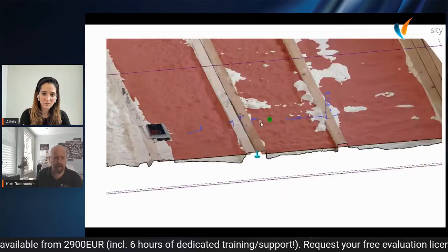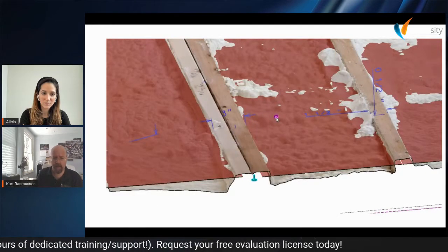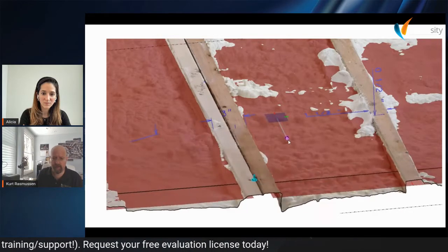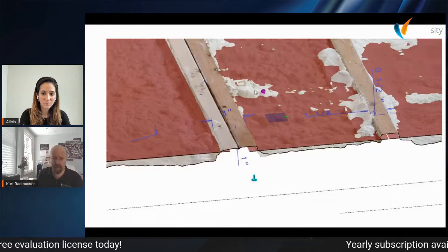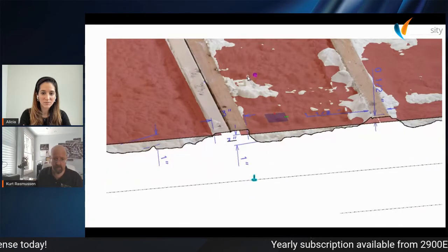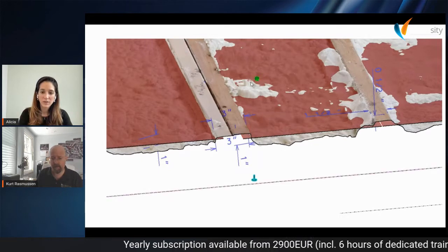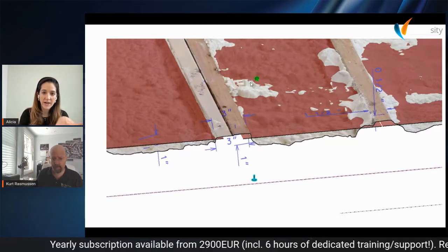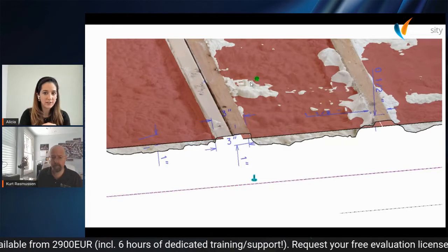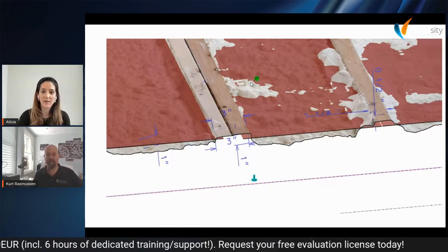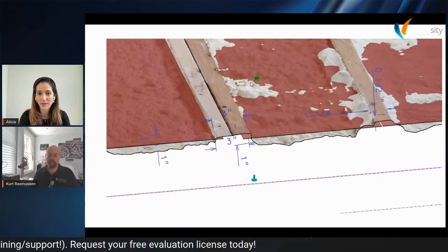Oh, actually, I don't think I put insulation in that bay or did this R value check. But you can see that I had some measurements there. I have the measurements of the studs. Those two studs together are 3 inches. And then you see here that I actually showed the depth of how much we were lacking underneath that R21 value. So the red indicates where the insulation should have reached, right? It should have been there. Yeah, okay. And the white is the actual insulation that they put. Yep.